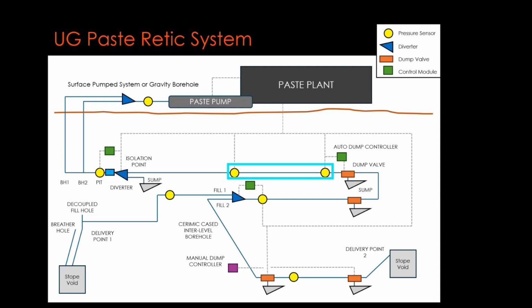This is the friction loss arrangement of two pressure sensors, P1 and P2. The difference between P1 in the upstream and P2 in the downstream, divided by the distance across them and any elevation change considerations, will provide a friction loss value.